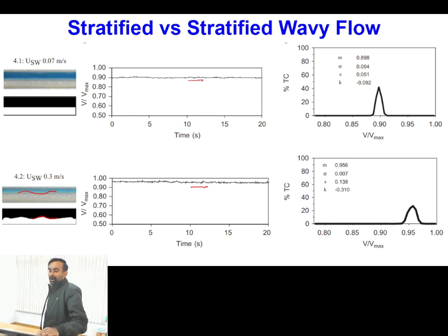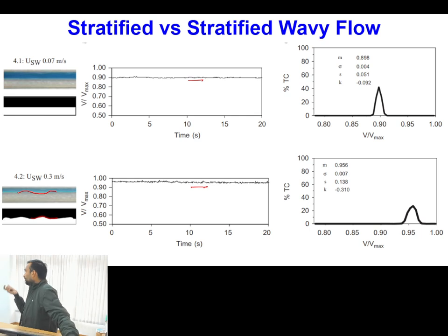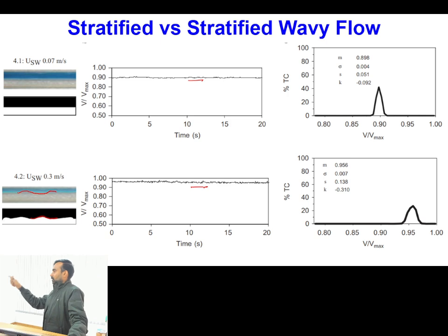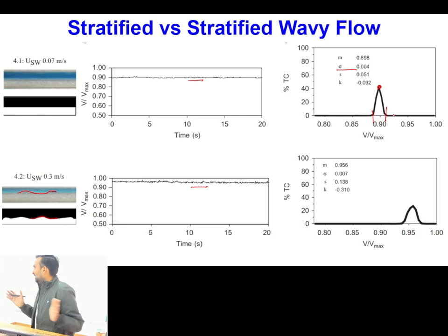So under this scenario, we can perform further statistical analysis of the signal, and depending upon the statistical analysis, we can come up with some specific statistical features of the signal which have identical behavior for one particular type of flow. For example, for this type of flow, the peak value of the signal is large and its standard deviation is less.